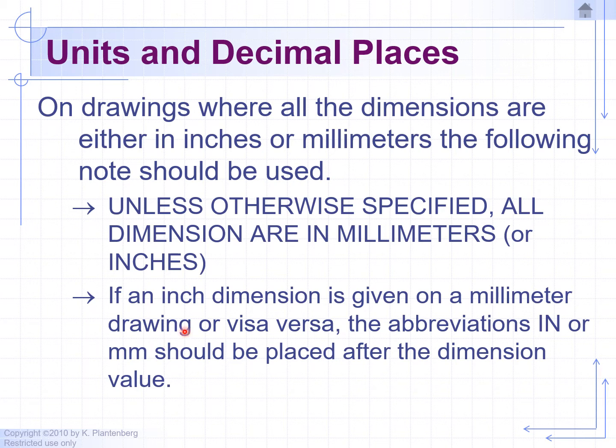Now it's very rare, but once in a while you will mix millimeters with inches. So on our previous slide, we were dealing with inches. So all the dimensions are in inches because it told us in the title block that all dimensions are in inches. It's very rare, but once in a while you will create a drawing where you have all the same units. For example, all the dimensions are in inches, but there's this one hole with a special size diameter, and the part that inserts in that hole only came in millimeters.